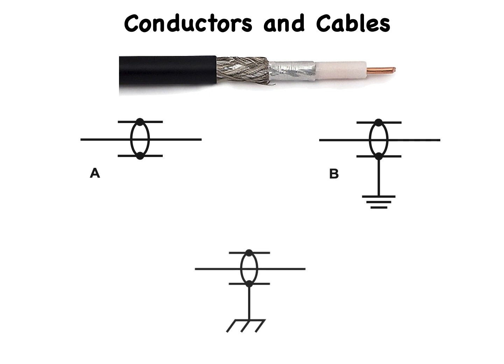At B, as well, this figure shows a symbol for coaxial cable when the shield connects to a chassis ground, such as the metal plate on which an electronic circuit is constructed. The chassis ground might lead to an earth ground, but that's not always the case. In a truck, for example, no earth ground exists, so the chassis of the trucker's CB radio would go to the vehicle frame.